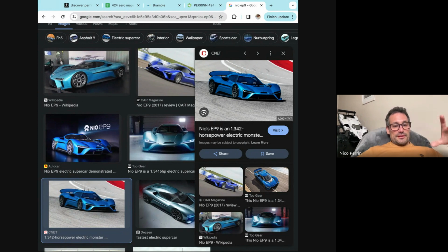And what we did is we fitted, like we always do, strain gauge on the push rods, and then we measured downforce on a straight line on an airfield, which we will do for 424. And it came inside 5%. When I say that, it means we measured downforce level with less than 5% error at different attitudes compared to the CFD.